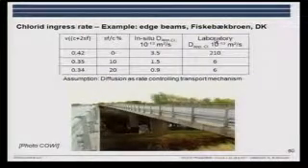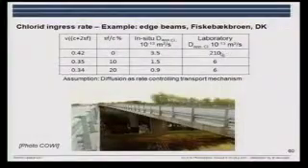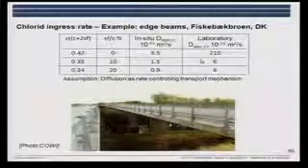Then they have taken cores from the back, or the non-exposed part of the concrete, and they have saturated them, as we do when we are doing chloride tests in the lab, and they have exposed them to chloride, a so-called bulk diffusion test, where you have the sample and expose it from one side for, I think it's 35 days, and then you do the same again: the grinding and the determination of the diffusion coefficient. And you can see a huge difference. For the larger one here, you have a much higher diffusion coefficient. And why that?